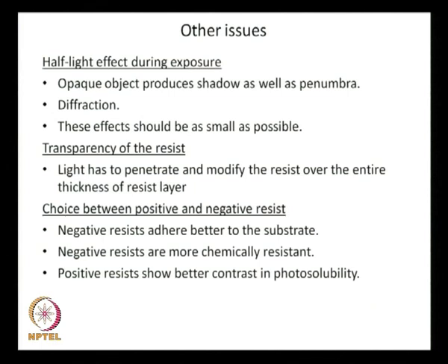Then there is this choice between positive and negative resist. You may ask, I have a choice, now which one to take? Now, the practical suggestion would be: negative resists adhere better to the substrate. Negative resists are more chemically resistant. On the other hand, positive resists show better contrast in photosolubility. So, these are pros and cons of these two resists, and when people develop protocols, they develop them based on these understandings.